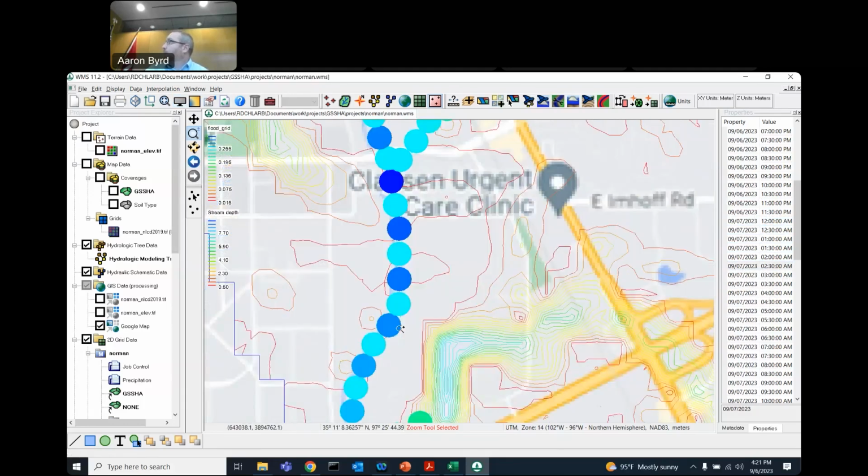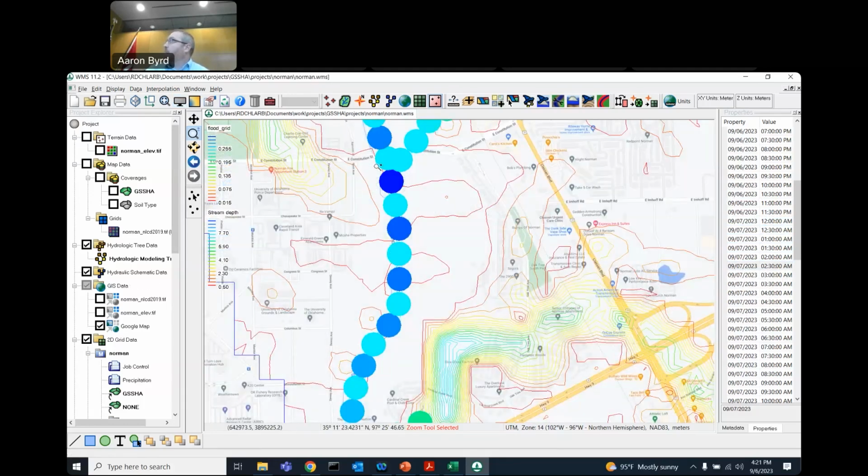So what do you notice right here? What's happening? It's oscillating. Oscillating, right? High, low, high, low, high, low. So you can figure out what's going on here. Probably the channel's not wide enough for my time step, what we said, a 1 meter channel or something like that. It's got a lot of water coming through here for a 1 meter channel.